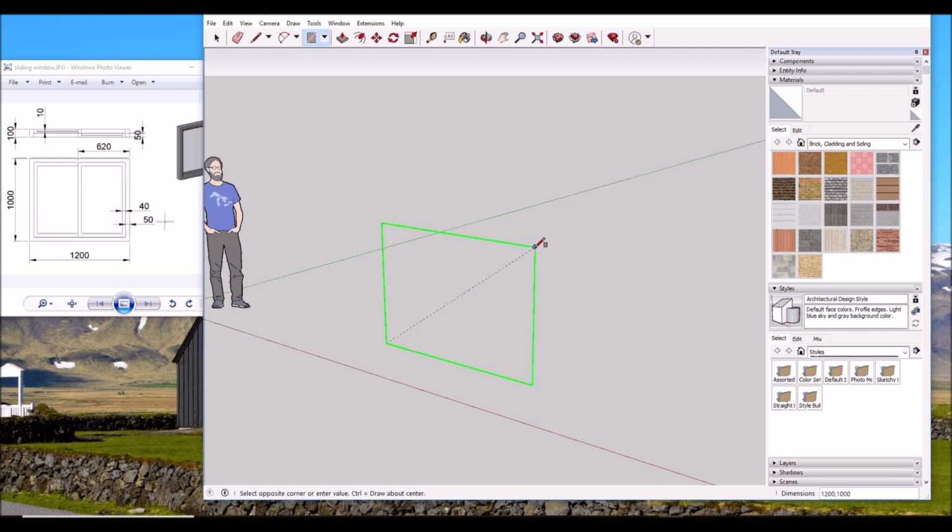Okay, this is exactly the same as AutoCAD. You type X, comma Y, and then you press enter. Make sure you use enter, don't use spacebar. Spacebar is enter in AutoCAD but not in SketchUp. So you press enter. Now you have created a rectangle. Whenever you create something which is closed, SketchUp will create a surface for you, so the white color means there's a surface inside.